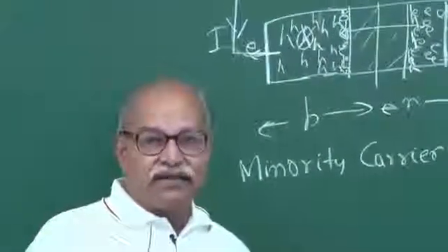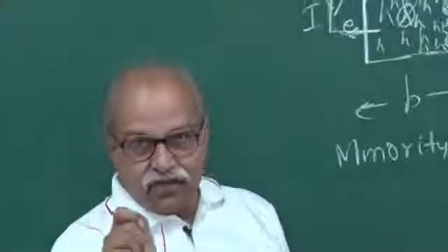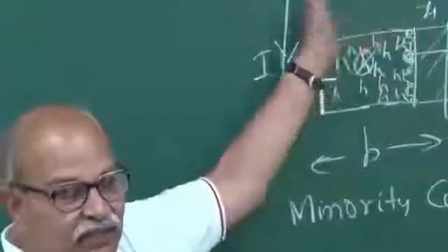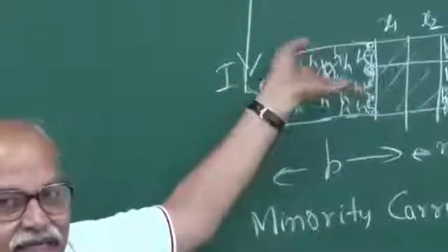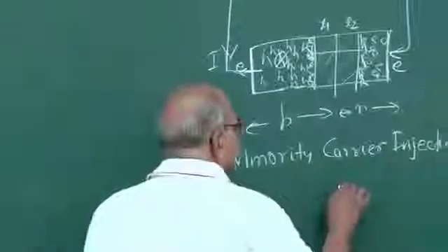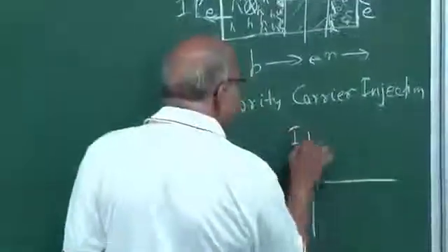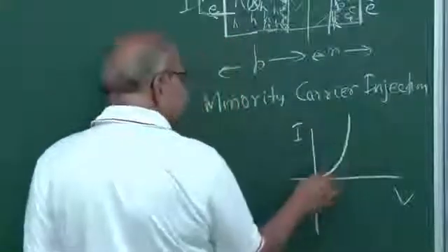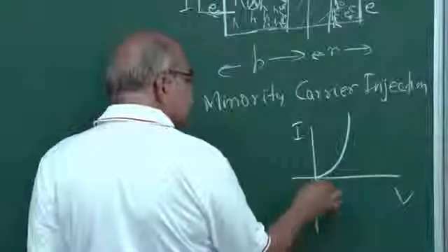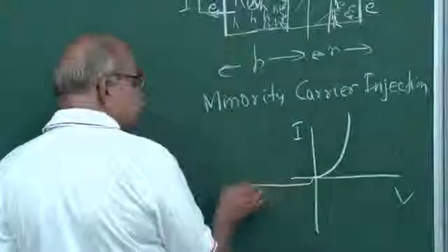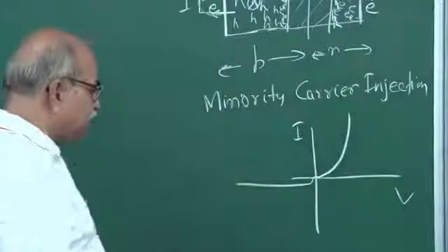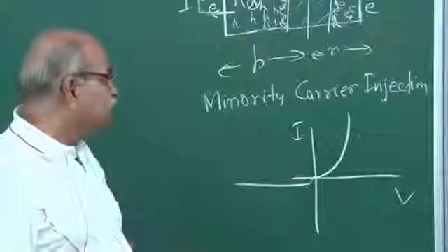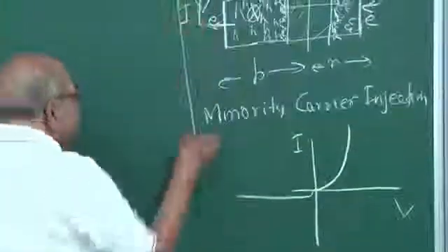And all these things are in a controlled fashion. You control that biasing voltage, and then you control all varieties of the phenomena here and the resulting current also. Okay. So on the forward bias side you had your IV characteristics going exponentially like this, whereas on the reverse side you have almost zero current, almost negligible current. If you change the scale here, microamperes, this is milliamperes, then perhaps you are able to see it on this plot. So this is what we discussed.